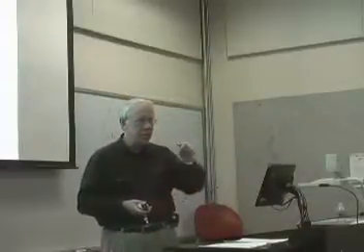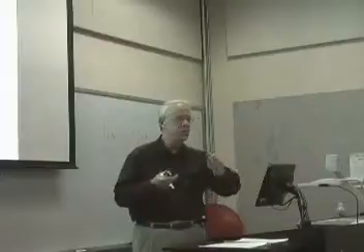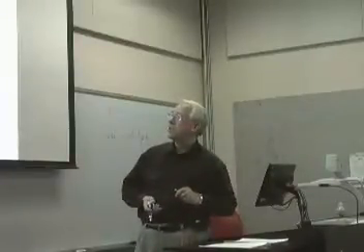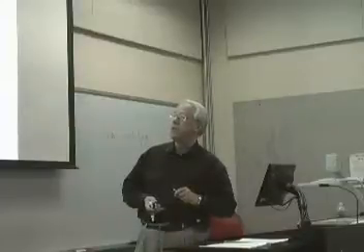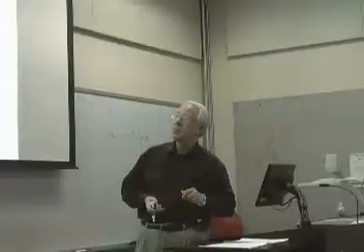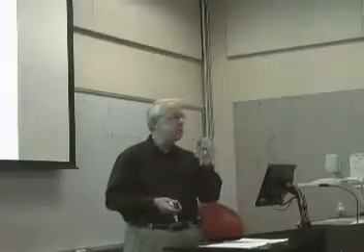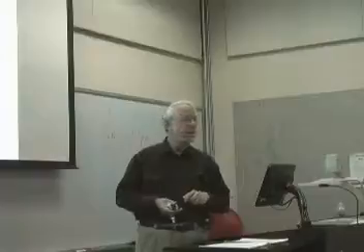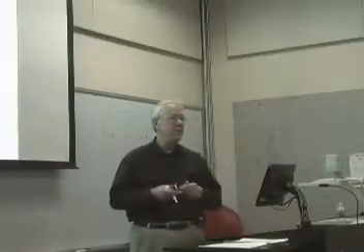So it's easy for you to go in and add what little values you need for the boundary conditions for this particular technique. So I expand T in terms of the shape function and the nodal values. I just plug this in here. Now by setting the weight equal to the shape function, that's why it's called Galerkin's method. In fact, if I set the weight equal to 1, I would wind up with the finite volume method. And so embedded within finite elements are a number of numerical methods, and it all depends on what you're going to be using for the weights.